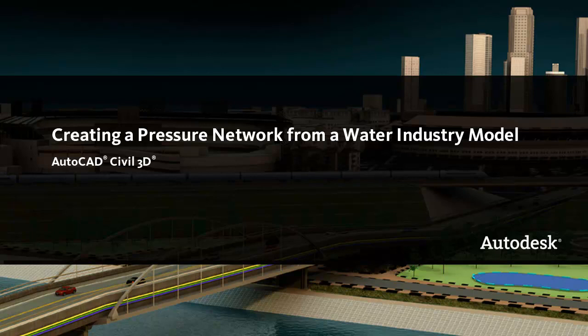In this video, I'll show you how to create an AutoCAD Civil 3D pressure network from a water industry model that was created in AutoCAD Map 3D. A water industry model is a specialized GIS schema that has feature classes, rules, and relationships for the water industry. Civil 3D can read the schema and quickly create a pressure network using specified parts and styles.